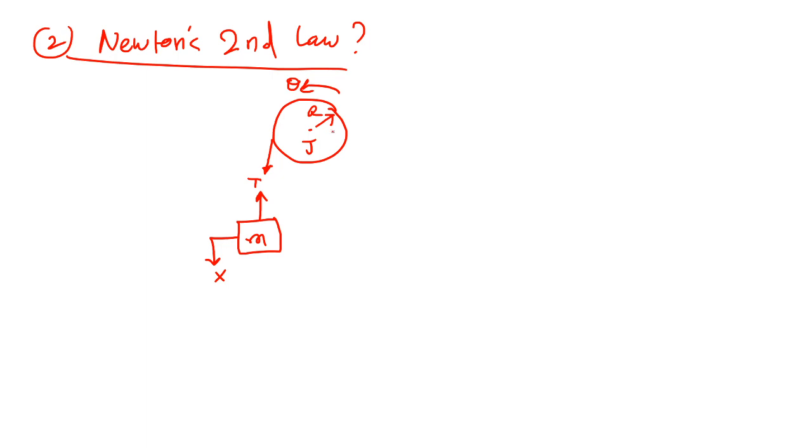And this pulley is rotating this side. So here we have a reaction force from the spring, always against the motion of theta, and it will be k r theta. Good? That's all. So this is the free body diagram. Now we're going to use Newton's second law, summation of forces. For which one? Be careful here. First, start with the degree of freedom.